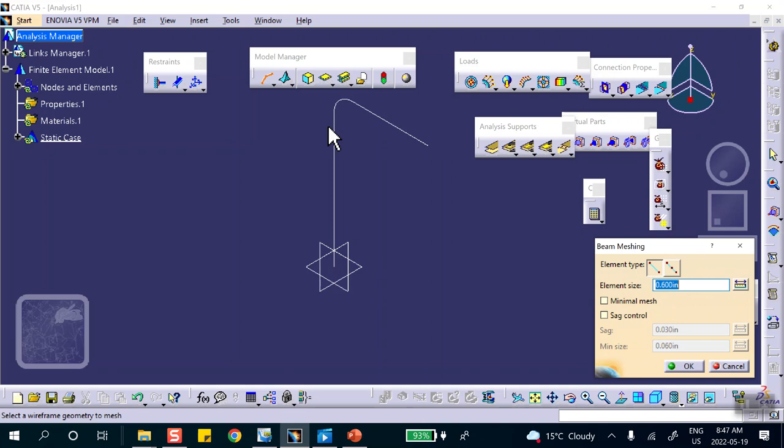If you go sketch route, you click on it, it turns yellow, good sign. It says what kind of element you want. I want linear. This is parabolic. I'll use linear. A size, I don't know, 0.6, 0.3, 0.1. These are so cheap that you can make it a micron probably, because remember, it's just a line, 2 degrees of freedom. Each node has, yes, 3 degrees. Each node has 6 degrees of freedom. Yeah, okay. But let's not be ridiculous. Let's make it, I don't know, 0.2. How about that?